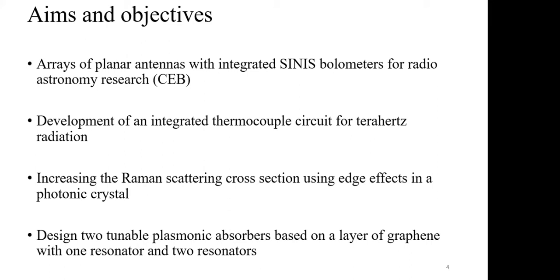Here our goals were arrays of planar antennas with integrated SINIS junctions or bolometers for radio astronomy research, and development of an integrated circuit for Terahertz radiation. Also to increase the Raman scattering cross section using the edge effect in a photonic crystal. Another goal was the design of plasmonic absorbers based on a layer of graphene, using 1 and 2 resonators. It's another approach.